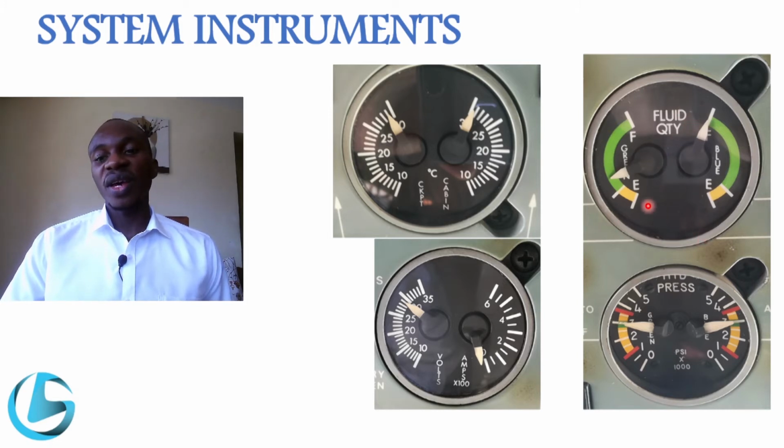On the right here, we have a picture that shows the hydraulic system indicators. And as you can see on this particular aircraft, you have two hydraulic systems. You have the green system and you have the blue system. This top gauge or indicator indicates the quantity of fluid in the hydraulic system. The bottom indicator is for the hydraulic pressure for the particular hydraulic system. For the green system, this one is in PSI, and as you can see, the pointer is pointing at number 3. This shows that this system has 3,000 PSI, or the pressure for the green system is 3,000, and the same for the blue system, 3,000 PSI.